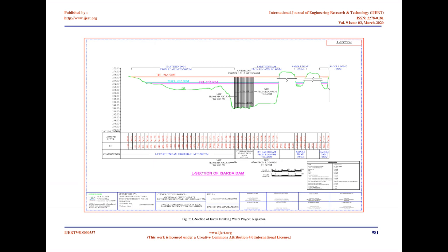Mica schist, phyllite, and quartzite belonging to the Hindoli group of the Aravalli supergroup are exposed in the project area. In the river portion, there are no exposures and the river channel area is covered by thick alluvial deposits and river sand. A small linear patch is observed along the left bank of the river exposing steeply dipping phyllites, schist, and quartzites. On the right bank of the river, a narrow low-lying strike ridge consisting of quartzites, phyllites, and schist is exposed and surrounded by alluvial and aeolian deposits.